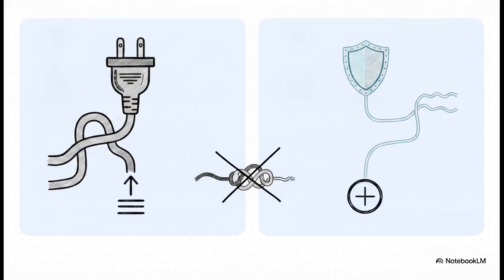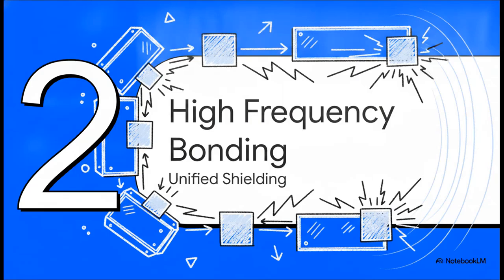So how do we fix this? Well, we have to strictly differentiate between our big, bulky power grounds, like your 50 Hz power or heavy DC returns, and our highly sensitive electronics reference grounds. Casually dumping everything into the same chassis ground is a massive, massive risk. Instead, you need dedicated ground returns. That negative reference has to be brought directly back to its intended return point. And sure, yes, this adds a weight penalty in platforms like aircraft, tanks, or ships. But you have to treat it as a totally non-negotiable requirement if you want to keep that sensitive reference shield clean and stable.